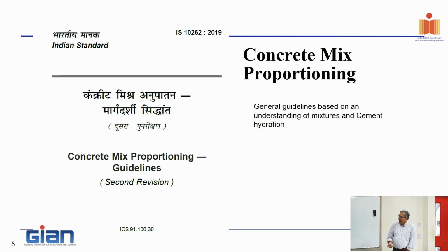And in India, we follow IS 10262, which is our base code. It's been revised, that I remember, twice. Now, of course, we have this in the bilingual format, which I find rather confusing, but it is available in the bilingual format now. And this gives us the general guidelines. What I want to do today is look at these guidelines available in IS 10262 and understand the basics of it. And believe it or not, a lot of these guidelines come from fundamental ideas of packing and what we understand about cement hydration and cement rheology.